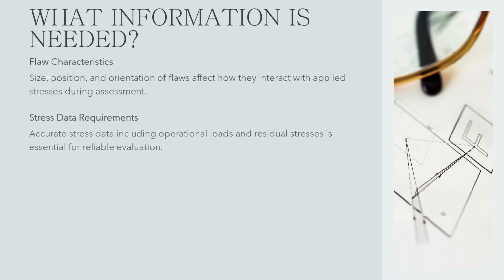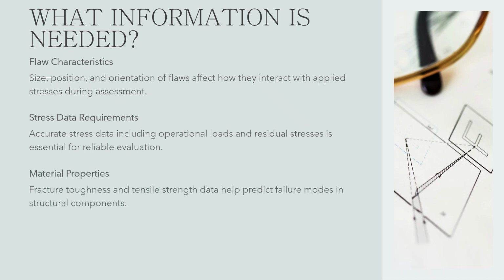Second, accurate stress data for the region containing the flaw is required, including operational loads and residual stresses from welding or fabrication processes. Third, material properties such as fracture toughness and tensile strength are critical for predicting failure modes.